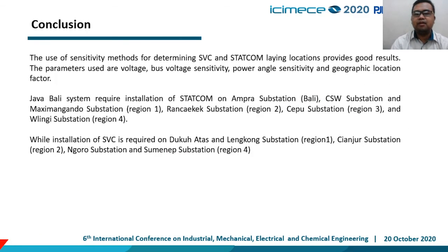So, from this paper, we can conclude the use of sensitivity methods for determining SVC and STATCOM laying location provide good result. The parameters used are voltage, bus voltage sensitivity, power angle sensitivity, and geographic location factor. Java Bali system require installation of STATCOM on Ampera, CSW, Maximangando, Rancaekek, Cepu, and Bangil substation. While installation of SVC is required on Dukuh Atas, Lengkong, Cianjur, Ngoro, and Sumeneb substation.